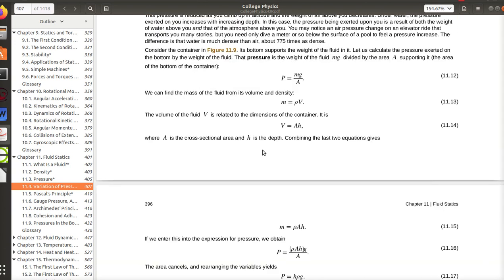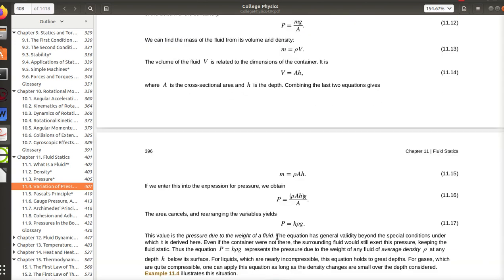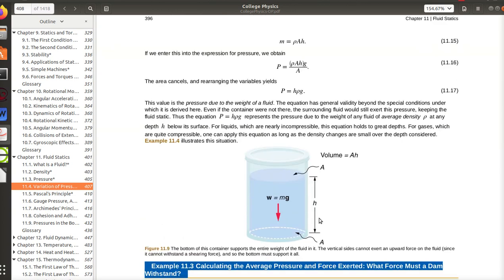So they're going to derive this equation. So pressure is height times the density times gravity, which sort of looks like potential energy, which is mgh. Well, m is part of the density, h is the height, and there's the g. So my pressure at the bottom is going to be greater than the pressure at the top of a liquid.